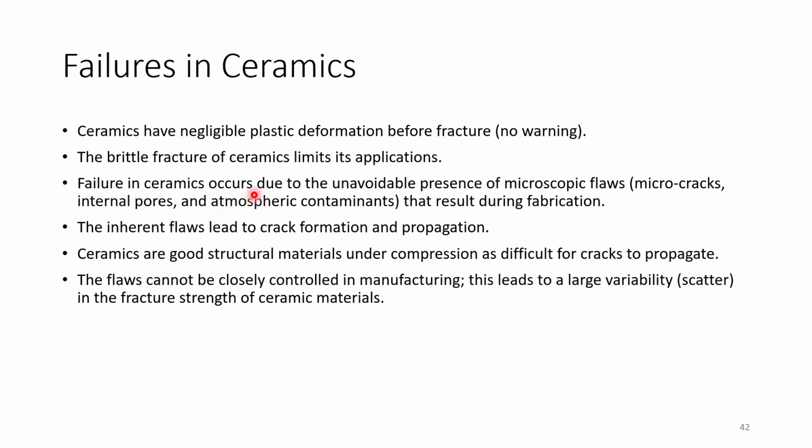Failure in ceramics occurs due to the unavoidable presence of microscopic flaws such as micro cracks, internal pores and atmospheric contaminants which result during fabrication. All ceramics are more likely to contain some pores or micro cracks already, which lead to their failure. The inherent flaws lead to crack formation and propagation.